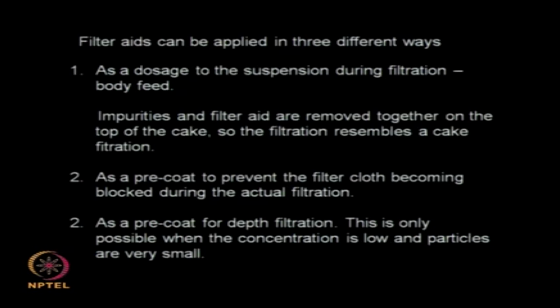So the solids settle down on top of my filtration aid, and they can be removed together. It is like a filtration process where I have the cake as well as the filter aid retarding the flow of the liquid.